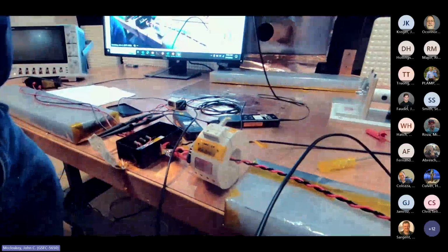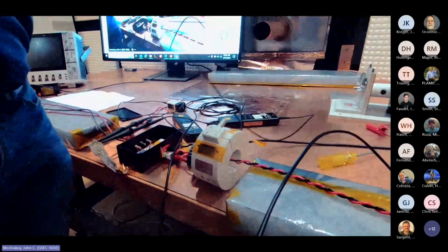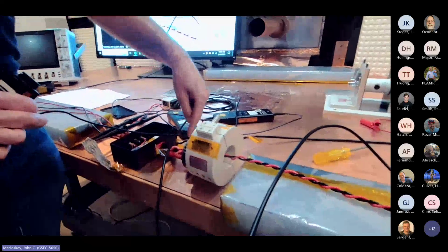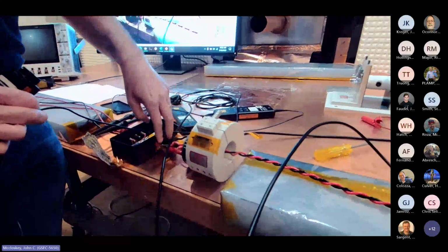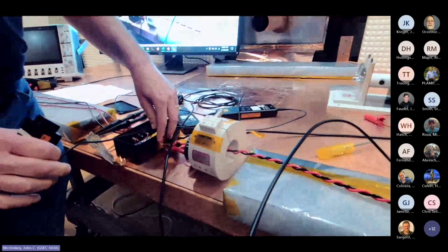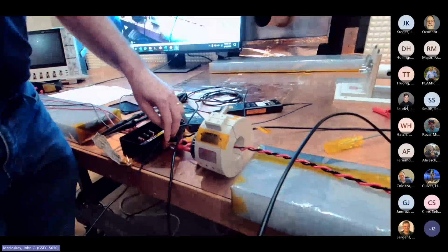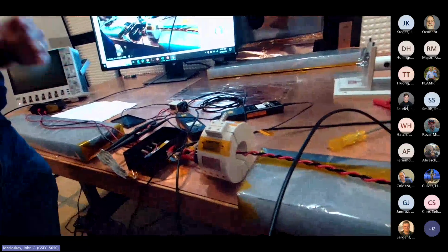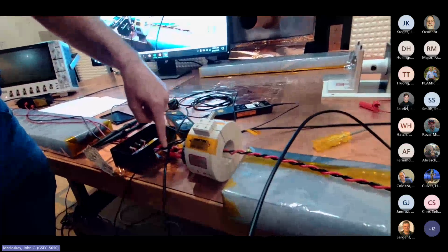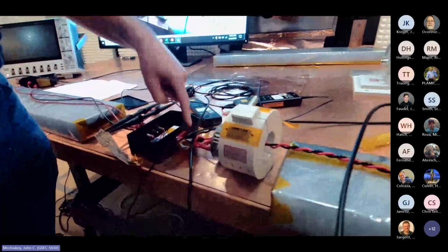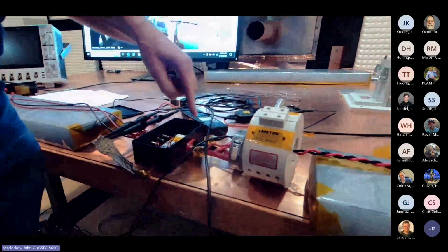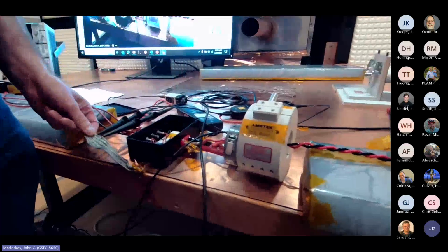So as I say, I have this differential voltage probe that we had been using for CS114 and such. It's still hooked up to our primary power input. You may not always have access to that, but I'm going to hook this up just because it gives us something else to look at. Now we are injecting common mode. Before, I had this hooked up differentially across the positive and negative terminals of the power input. But because we're injecting common mode, I'm more interested in what is being injected on this point with respect to the ground plane.